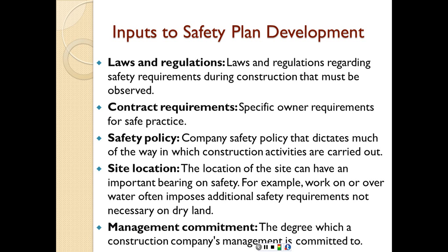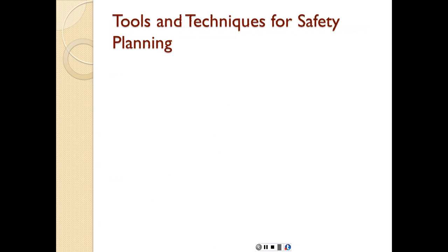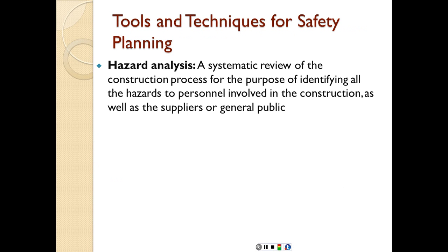The management commitment is the degree to which a construction company's management is committed to safety. The tools and techniques include the hazard analysis, which is a systematic review of the construction process for the purpose of identifying all the hazards to personnel or equipment or property involved in the construction, as well as suppliers or general public. Again, you might not only affect people who are working on site, but people who are living close to it or working close to it as well.